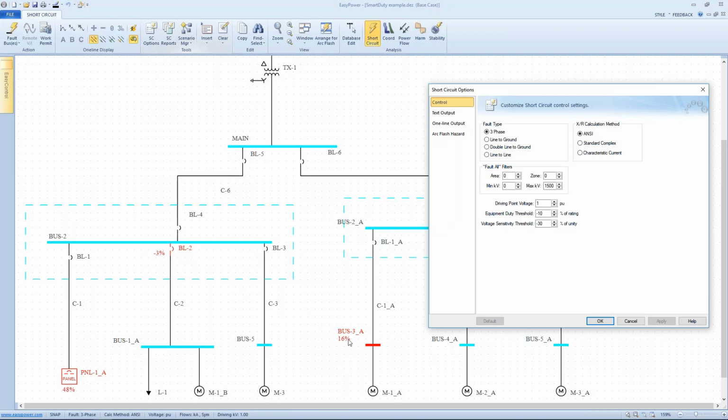The positive numbers show that we violated the specification, and that's how much excess current is being applied to that component. If I want to look at more elements in the system, I might lower the threshold. So instead of a -10, I might say -55.